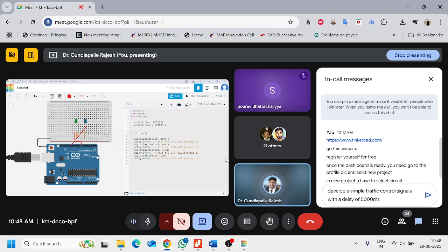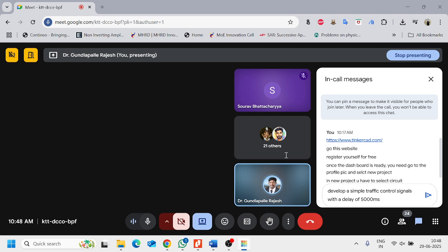Let us see how to change the delay before this. Here I have kept 1000, right? Now let us say after becoming low, I'll put only 100. I'll change the delay to 100, which means 0.1 second, and run it. So it is flashing, isn't it? You can just change the things and do this.